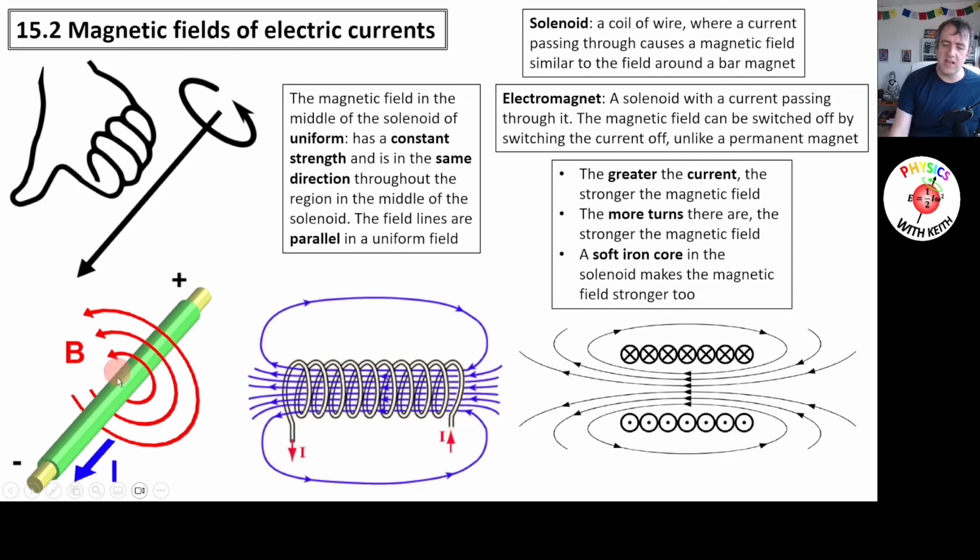Oersted identified that these, I mean, we haven't drawn the whole loop here, but this should continue. Let's try and get my pen. That should continue round in closed circles like this. He discovered that there were these circular magnetic fields around current-carrying wires. There's no North Pole, no South Pole, because there's no point from which the fields are emerging or to which the fields are receding.